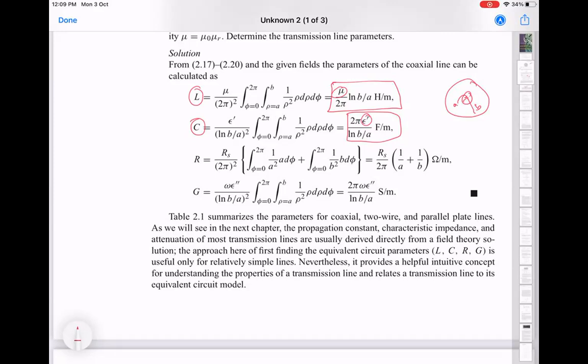It's basically a shielding effect, which is now becoming less effective. So one way to think about it is that if you have a metallic ground plane, and at some height you have a wire. So I've sort of cut the coaxial cable and made it into a flat thing. The inductance of this wire actually depends on whether another piece of metal is coming close to it or not.